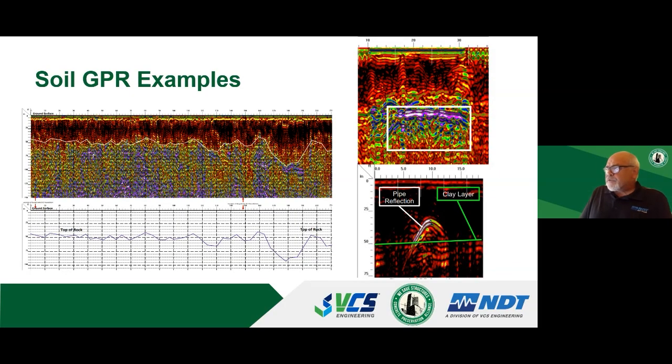Example of the results for some soil, the large plot on the left is a bedrock profile. That's down about 50 inches, so 4 or 5 feet. Continuous line of the rock. This happened to be associated with some cell tower investigations. Those guide wires that come down from the cell tower, what are they anchored in? Are they on just a spread footing, or are they doweled into rock? That makes a big difference as far as the load rating of the cell tower when additional antennas are going to be installed.